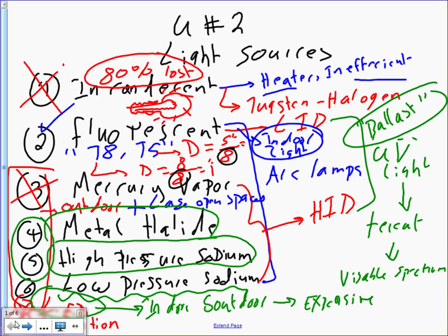It's a big deal. If you go to page 20, they have lumen and life characteristics of high intensity discharge lamps. They're comparing a bunch of them. First they have metal halide and high pressure sodium. I want you to look at this curve and tell me you can see that metal halide and high pressure sodium are superior, because after 24,000 hours, they will maintain 80% of their lumens. Can you see that?